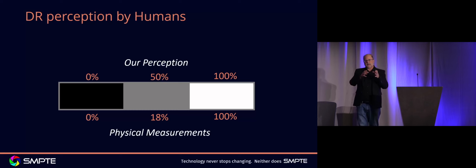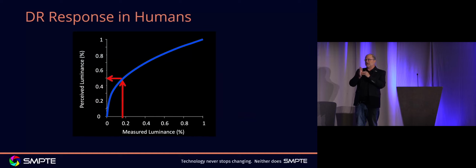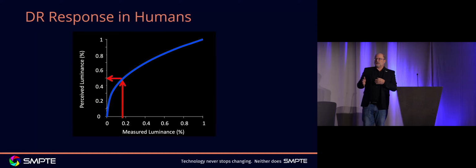So light comes into the camera as photons. The photons will hit the sensor. They will displace electrons, which will create an electric current. We measure that current, which is an analog value at that point, and then we will digitize that value using an analog to digital converter. That will give us code values. So that's the optoelectronic transfer function, taking light measurements into electricity and giving them certain code values, what we call the OETF.